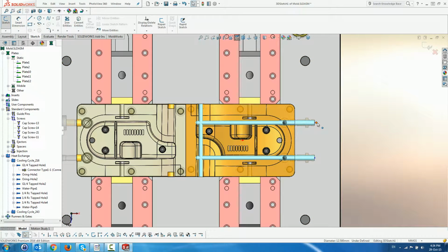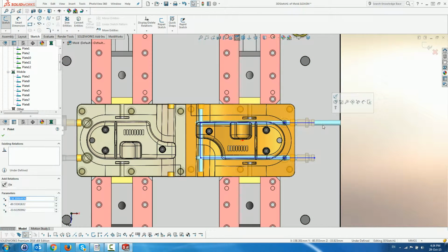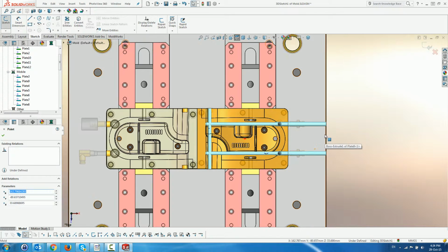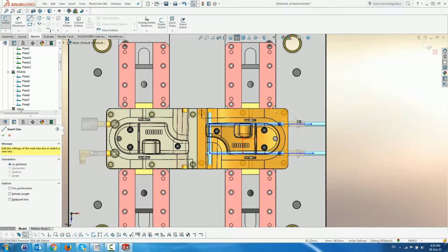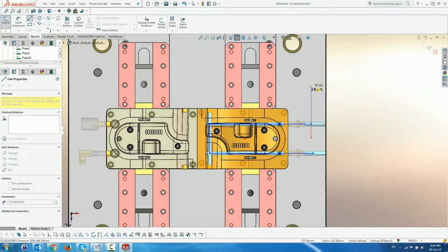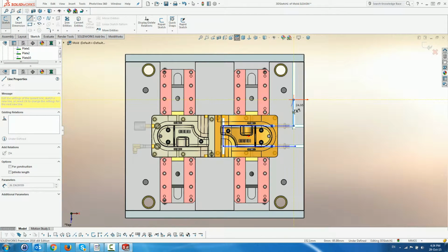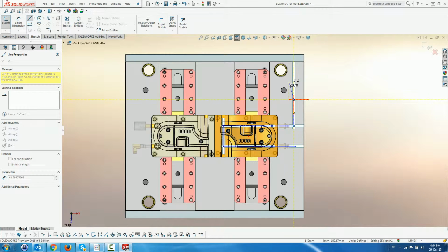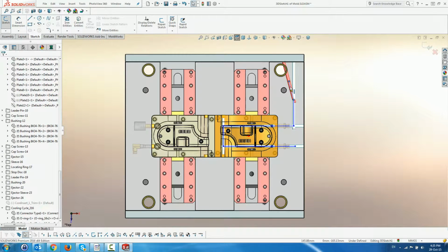Selecting a sketch endpoint and moving it dynamically updates the preview by extending the pipes to the plate faces. Furthermore, we can add segments with the sketcher, and the pipe cycle updates the previewed pipes dynamically, even showing collisions when they occur. We delete these extra pipes by deleting the segments and close the sketch.